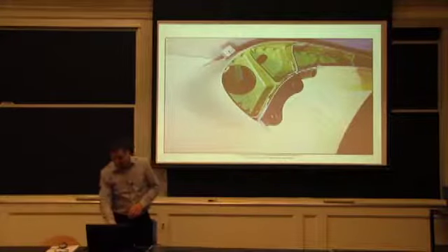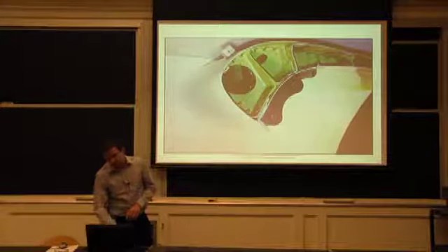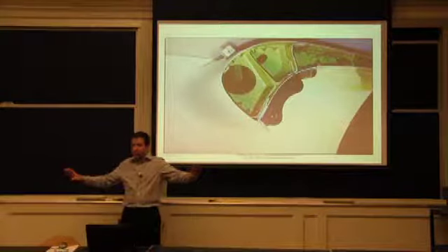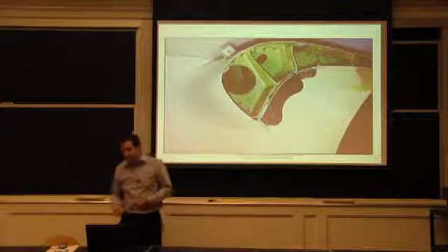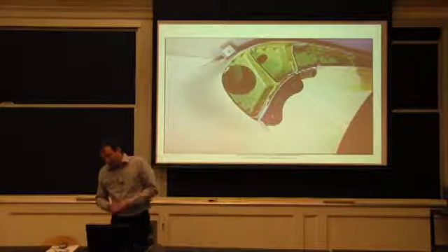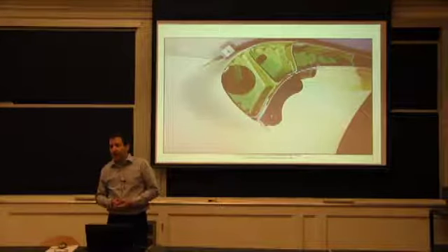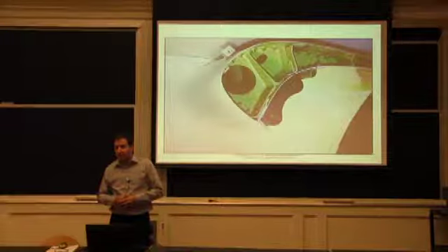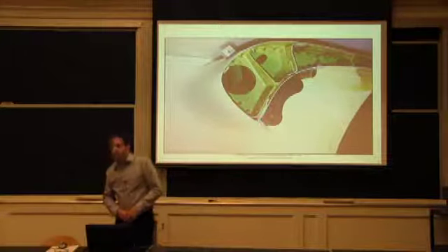When it's on the interior, here we have the benefit of looking at a cut piece. This was a test piece. But in reality, this wing is long, and you don't see all the ribs. So you don't see all the green pieces. So when we're talking about an acceptance criteria for a crack length, it would have to be a very long crack. It would probably have to be a fail-safe way of designing if you were to say, I'm going to allow this component to crack.